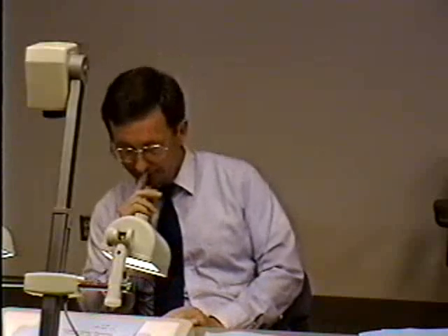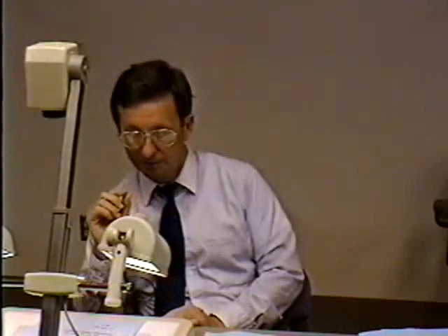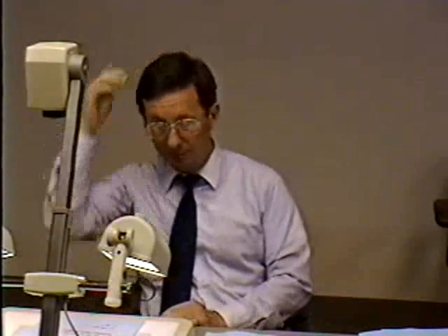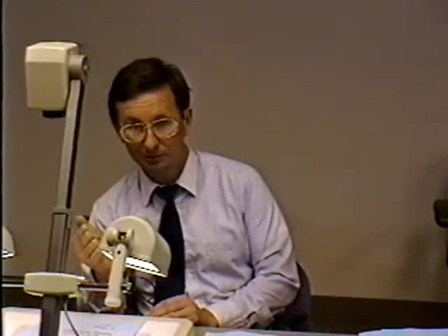Basically, when we're talking about the cavitation problem, it's a matter of you can't get the pump too high in elevation or the flow rate too great, because of the three forms of energy: elevation head plus pressure head plus velocity head. If you get the elevation head too high, it takes away from the pressure head. If you get the velocity head too high, it takes away from the pressure head, and velocity head's directly related to the discharge rate through the system.